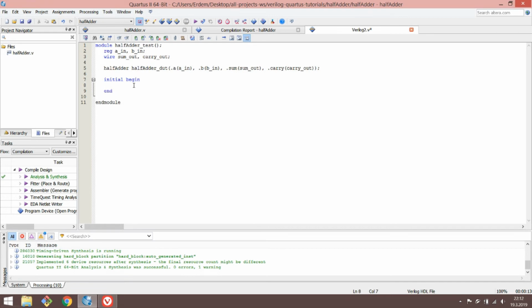Initially, I will read some memory, right? Then the keyword is readmem. We will specify the input as binary, so I put a B here. So it's readmemb. If I were to write it in hexadecimal format, I would write H here. Put a comma. It has two inputs actually. The first one specifies the directory, and the second one specifies where you want to store it in the test bench.